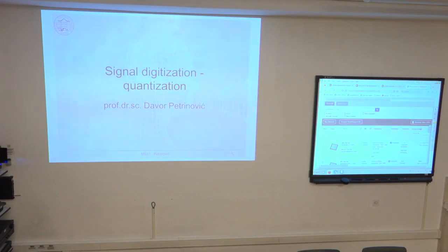A similar architecture is also used as part of a CCD, for scanning your camera picture, let's say. They have this CCD sensor, which is essentially a set of capacitors that have a charge proportional to the number of photons that fell on each particular sensor.